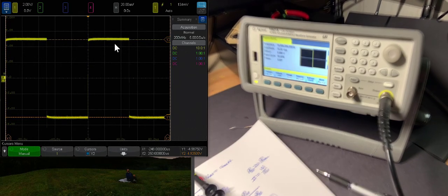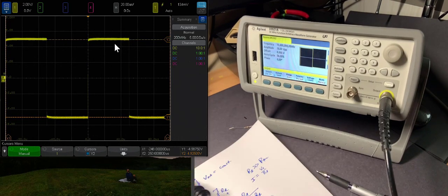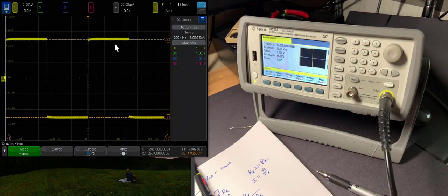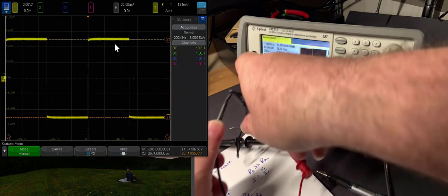While we're here, there's one other trick that I find useful to take advantage of. We have a pretty good looking signal. This waveform coming out of the function generator is a pretty clean square wave. And we have a pretty good connection between the signal and return. We're going to take this waveform and we're going to change the interconnect. We're going to do things that are wrong. We're going to make an error, but a known error, in order to see the signature of its impact on the measurement. I'm going to disconnect the return connection.